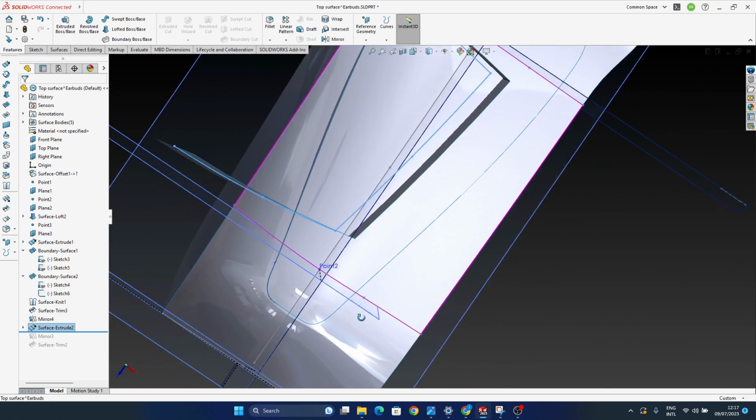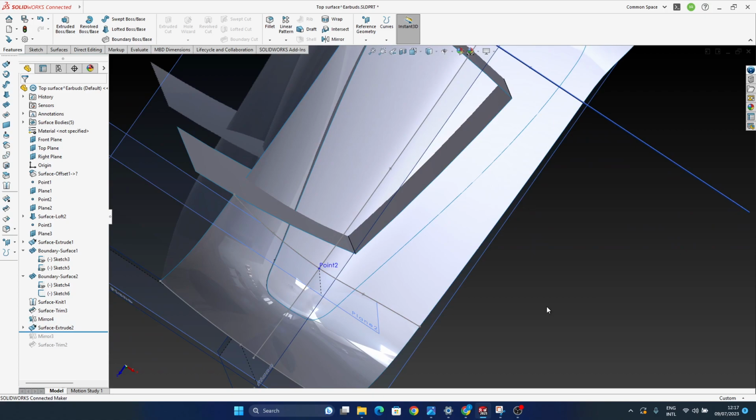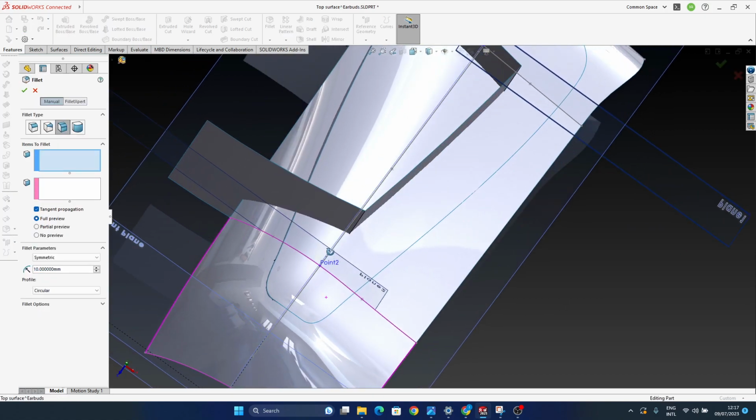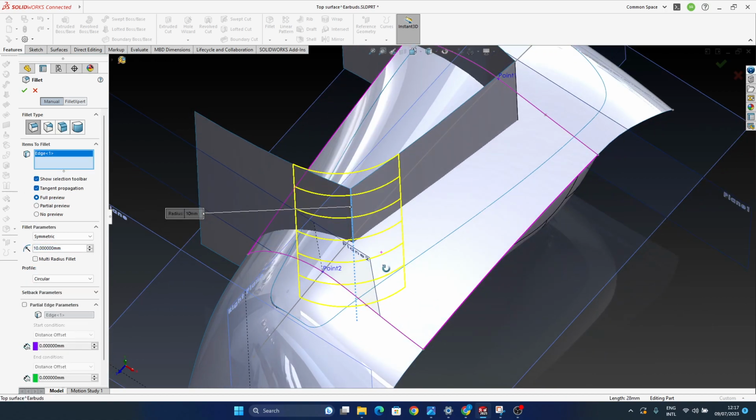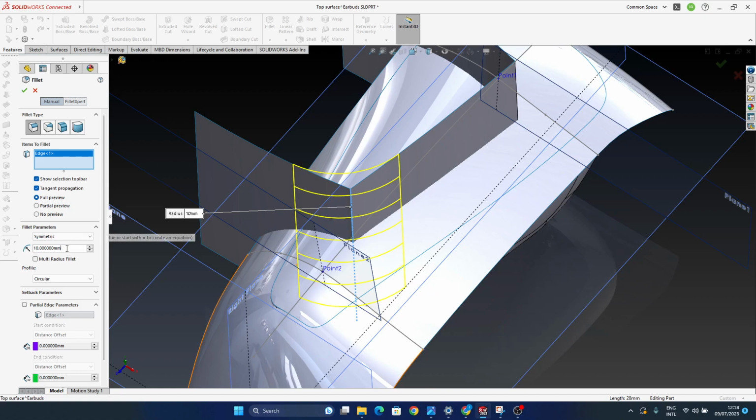with this surface. Let's try something fast, because I want to have the fillets done already when I modify everything, rather than cutting and making them afterwards. So I will try this with about 3 millimeters, should be just fine.